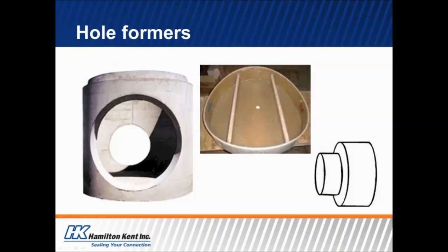sometimes that's not possible. And while the hole formers are reusable, they are still expensive. They can be broken, and they do take labor in order to secure them to the inside of the formwork. So there are some cons and downsides to a hole former as well.